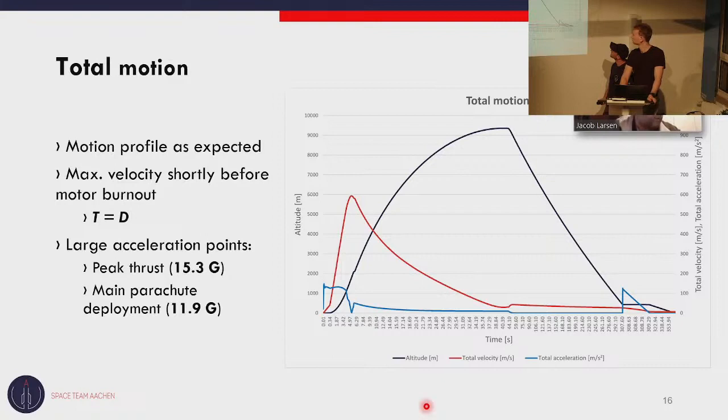Okay. This is a continuation of that question: have you been considering the effects of a so-called backflip? What has been seen on several occasions is that the lateral velocity is higher than anticipated from the simulations, and the deployment of the drogue chute will cause a significant braking force, which causes the entire rocket to flip very quickly due to the changing motion, putting the back end of the rocket first. Have you been considering some of these effects on your recovery system at this point?